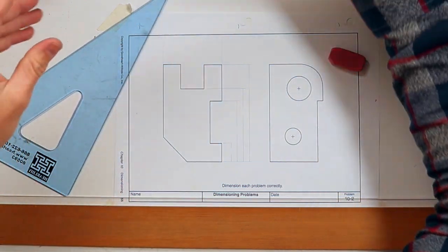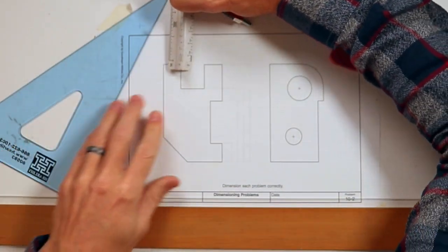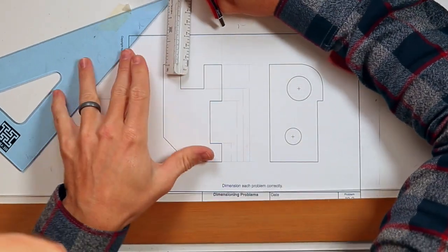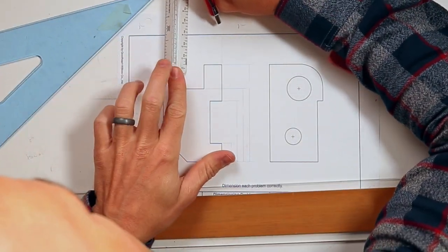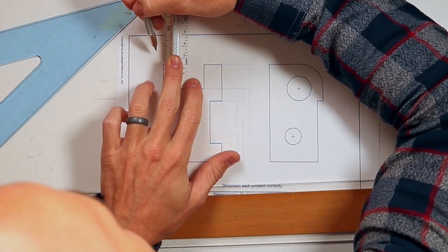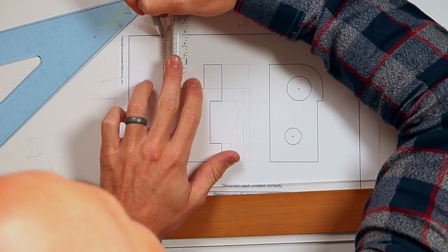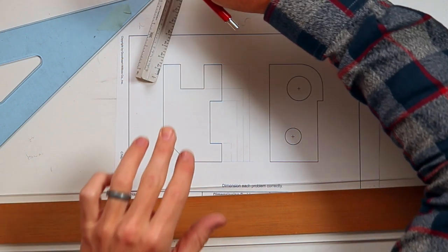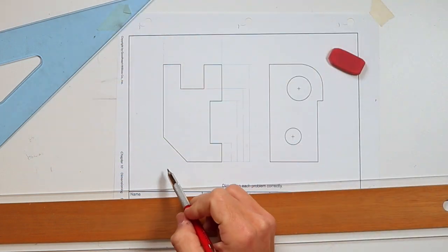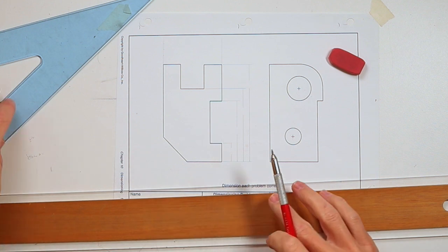Then I'm going to go and measure out the distance for my dimensions from the part. I have 4 of those, so I'm going to mark out the first one 3/8 away from my part. 1, 2, 3, and then 1/4 for every consecutive dimension. 1, 2, 3. The other reason I'm doing the angle down here is because I'm running out of room. You are going to face this as you get into more complex drawings that have a lot of dimensions.